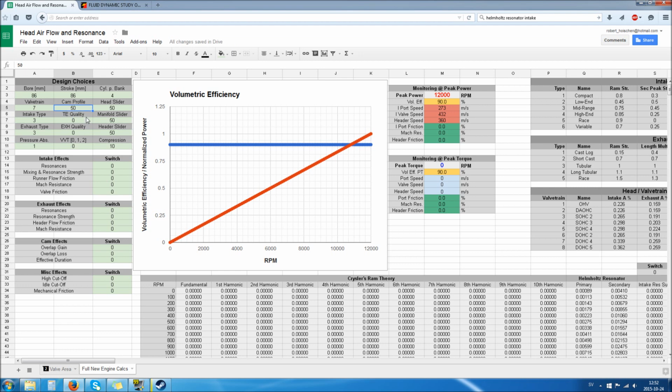And you would, from a very naive standpoint, which kind of makes sense but is very static, estimate that a valve has to be open for 180 degrees of crank angle. And that's very reasonable, because that's like the intake stroke length and the exhaust stroke length, right? That's 180 degrees each. But the engine is moving so fast that you basically have to open the valves earlier and later to make the air flow properly through the engine, and that is causing durations of more than 180 degrees of crank angle.